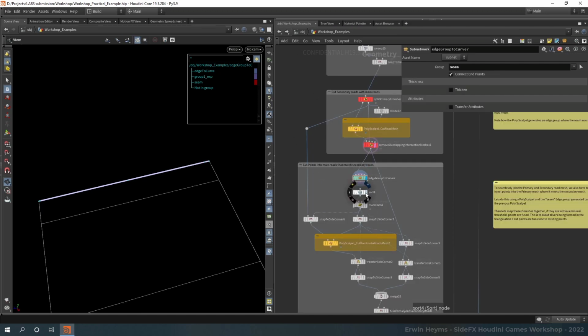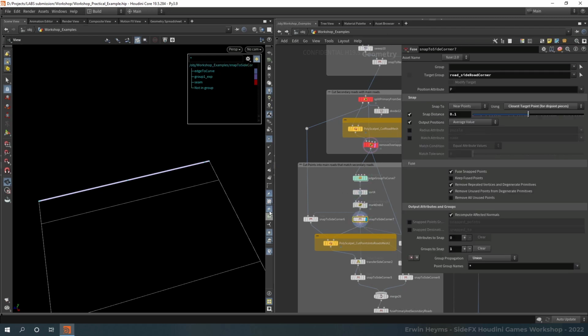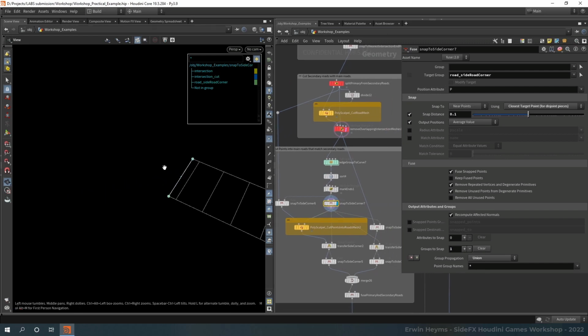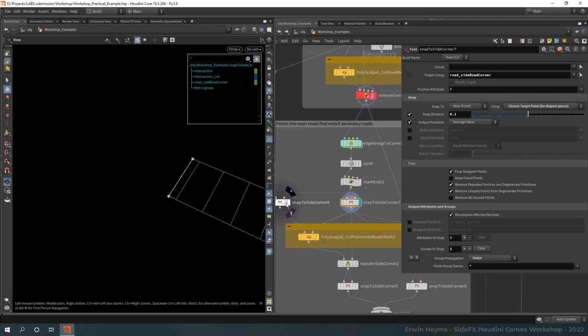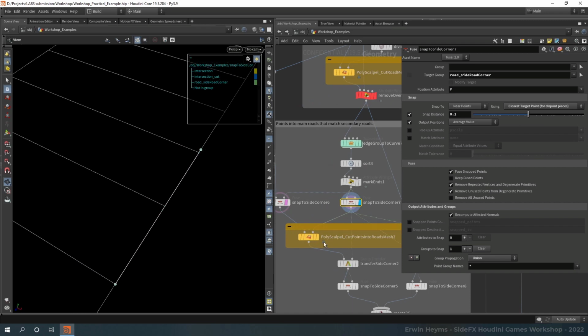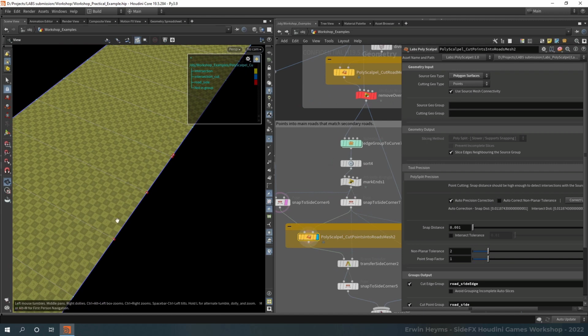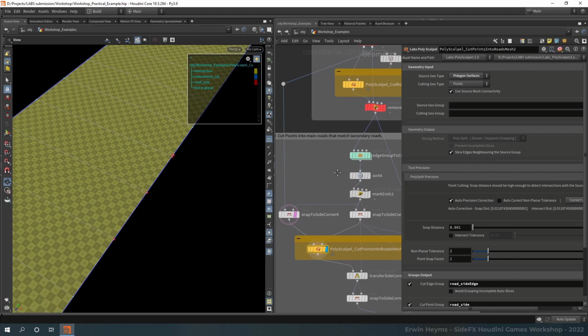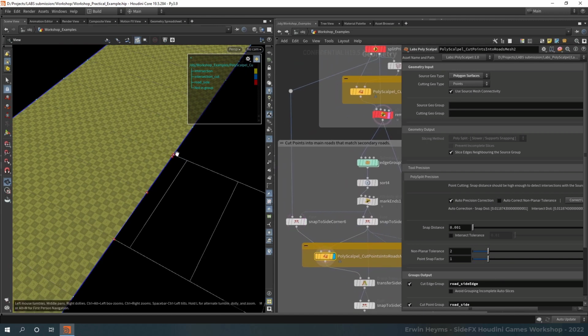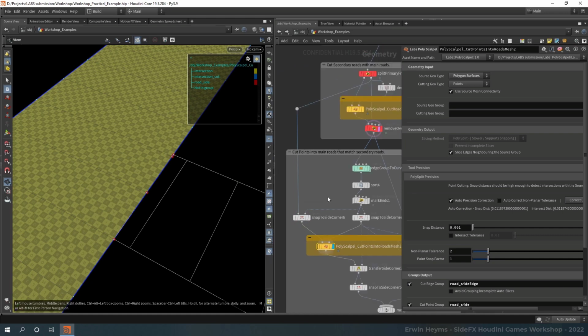And then we can run that through a couple of operations to create a cutting shape. Now with this shape, we can overlay it on the main road and inject some points. So there we go. We now have points that match the side road, and that should now work properly if we want to connect them together, because now both roads match each other.